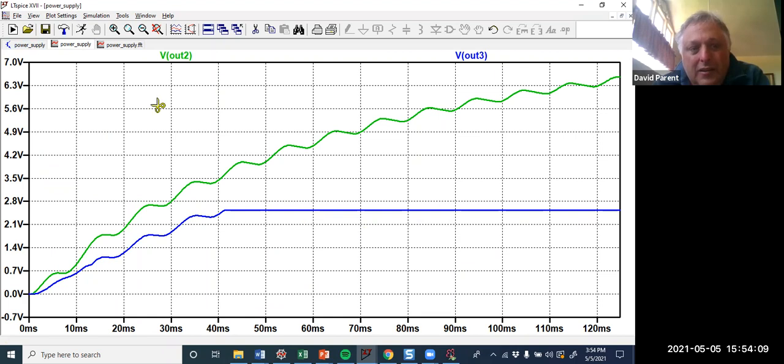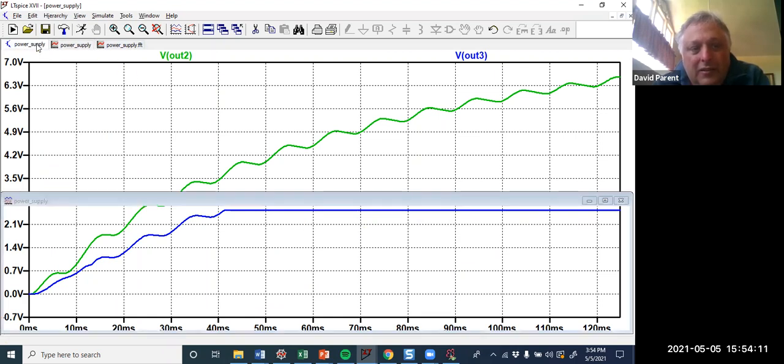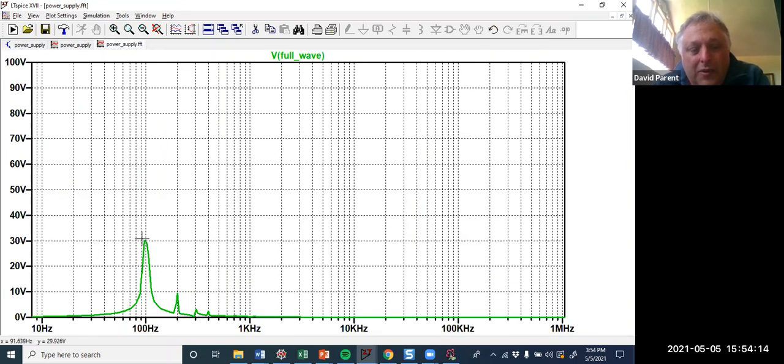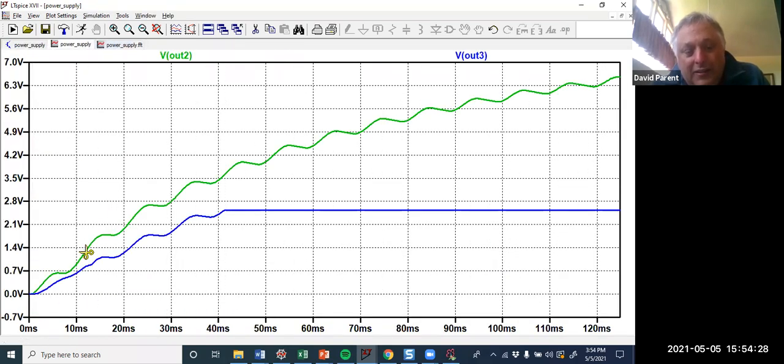All right. So really, we had these frequencies, and notice it's at 100 because taking the absolute value or using a full wave rectifier doubles the frequency. We got rid of these with a low pass filter, but it had a time constant, right? So it's taking 5 tau to reach wherever it's going.